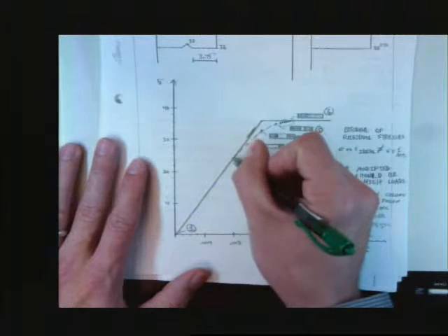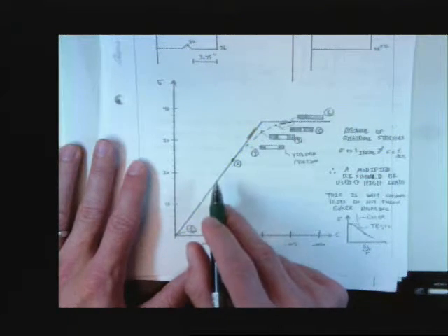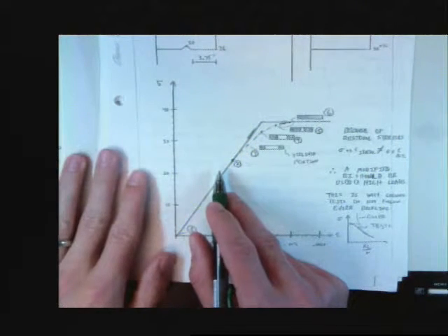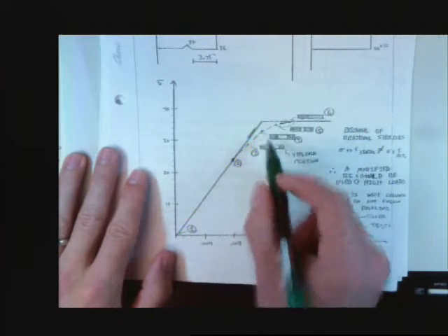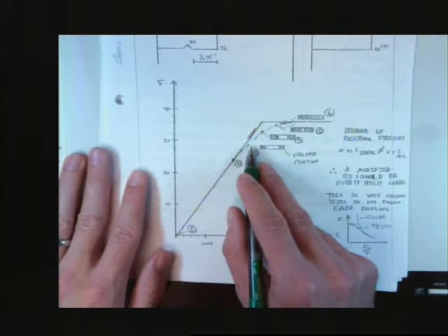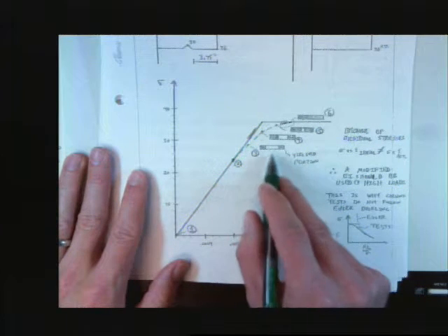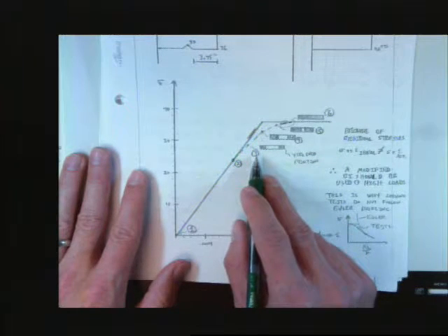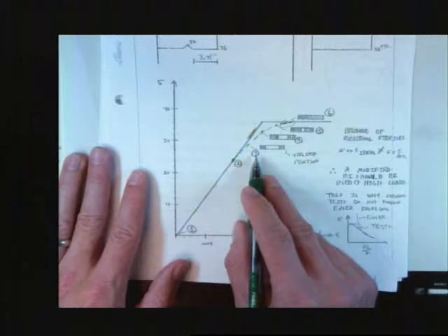After you get to about, I think it's around 44% of your yield, 0.44 times Fy, that's when this starts to no longer be linear anymore. That's when all of a sudden you start to get some nonlinear portions. You start to get some areas that are yielded in your cross-section. Depends on the residual stresses. Depends on the size of the member and the type of the member. Okay? We don't like to think about that.